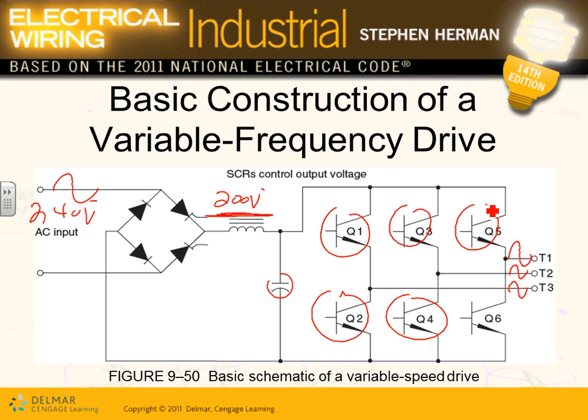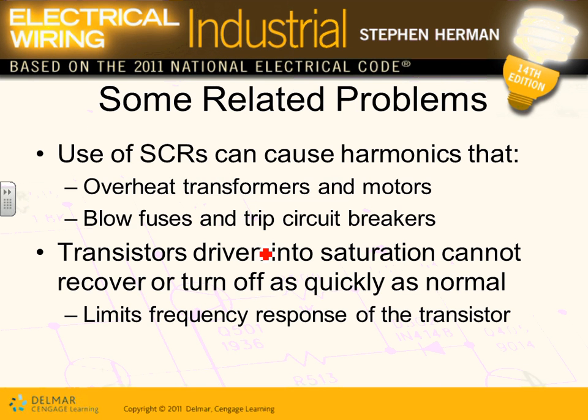Very simple. So you take the AC here, convert it to DC, control the speed, control the level of the DC, and then inject it back at a different frequency at a different time, guys. By doing it this way, they can control the frequency, which controls the speed of this motor. That's basically the principle of operation of a VFD: convert AC to DC, control it, and invert it back at the right frequency and right voltage to control the speed of the motor.